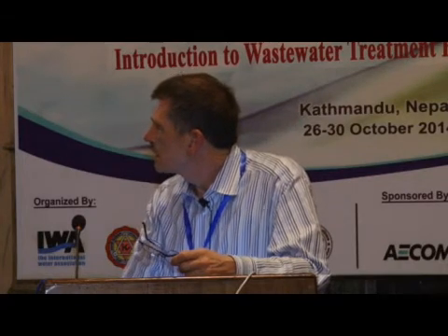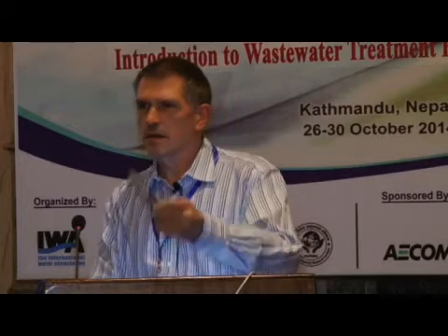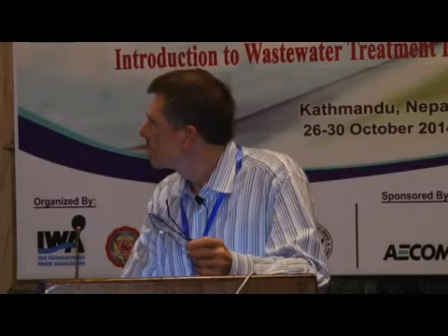And then there is that zero DO that I think Karthik explained in the influent, and 2 milligrams of DO in all the reactors, the diffusers, because there is a high oxygen uptake rate. You see that here it's 73 milligrams of oxygen per.